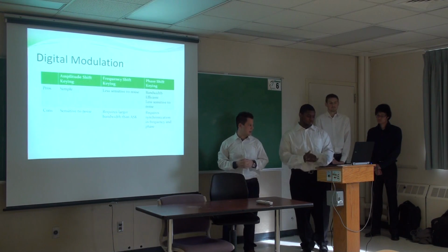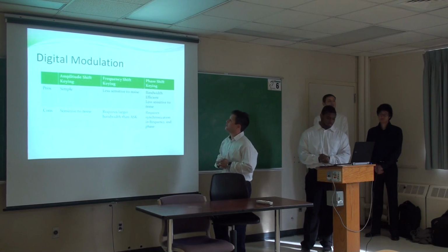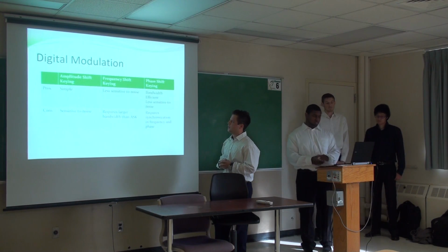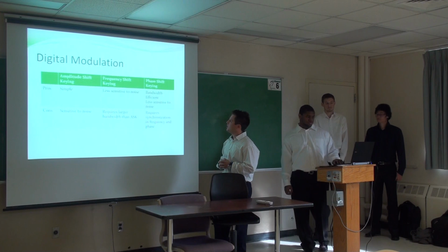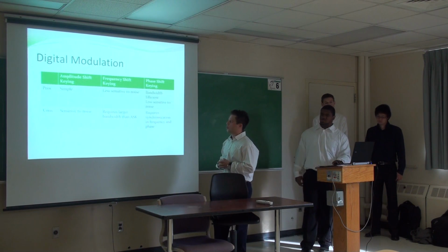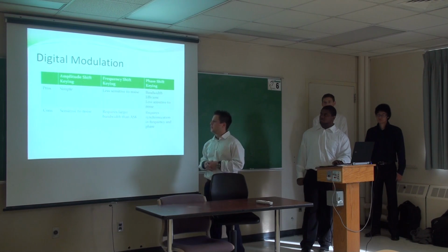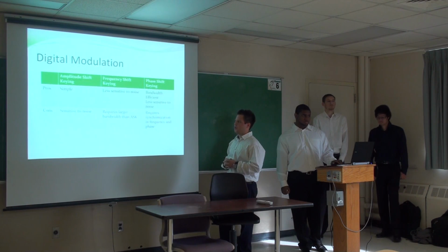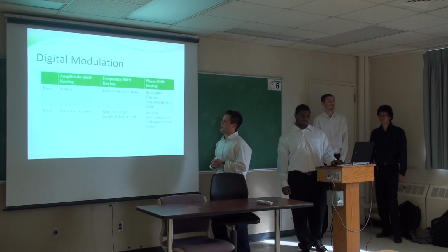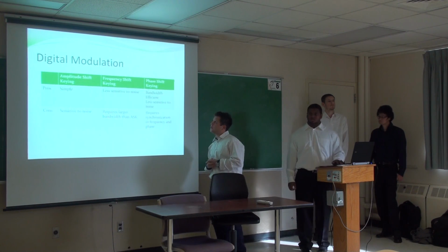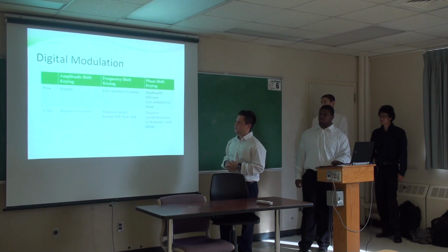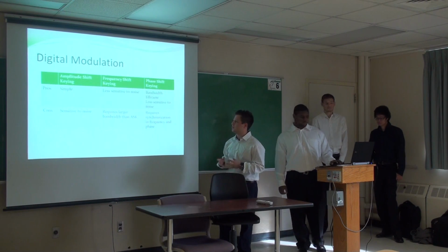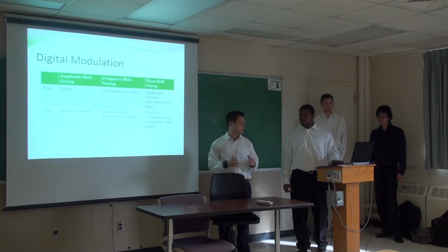The next one is digital modulation. Here are some digital modulation techniques: amplitude shift keying, frequency shift keying, and phase shift keying. They correspond to their analog modulation techniques and have the same or similar properties as the analog modulation techniques do. Keying just refers to being of the on-off variety, meaning that it has a binary modulation technique to it.